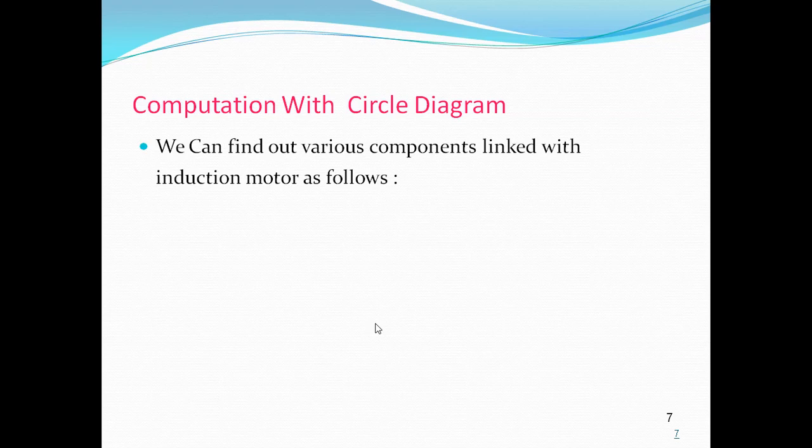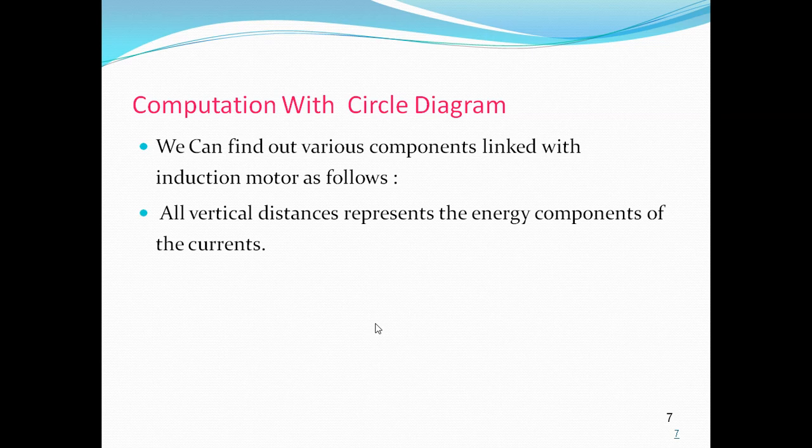So we can find out various components. From this circle diagram for the required induction motor, all vertical distances represent the energy components of the currents.